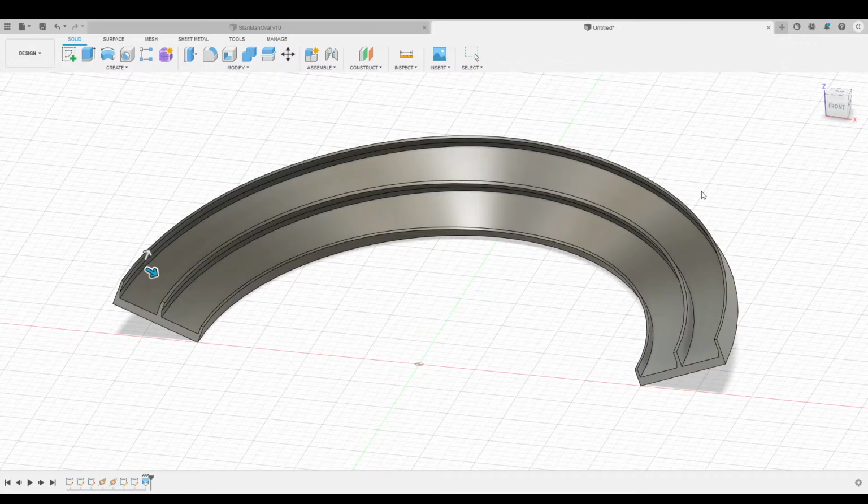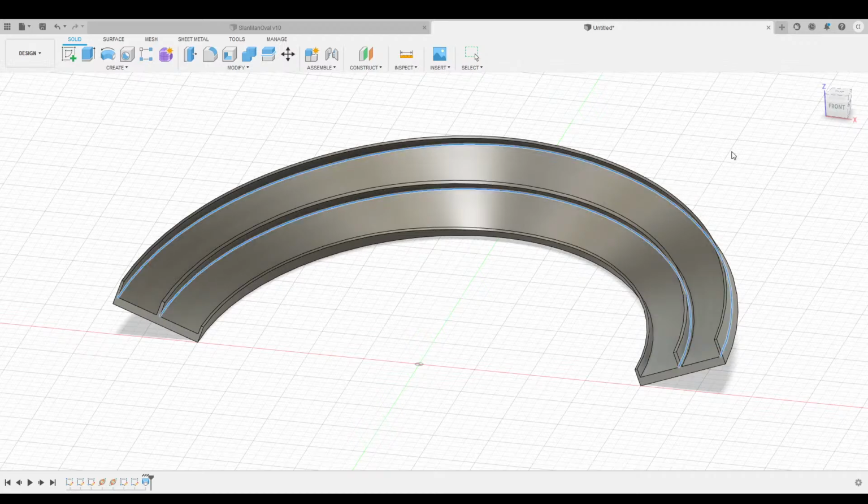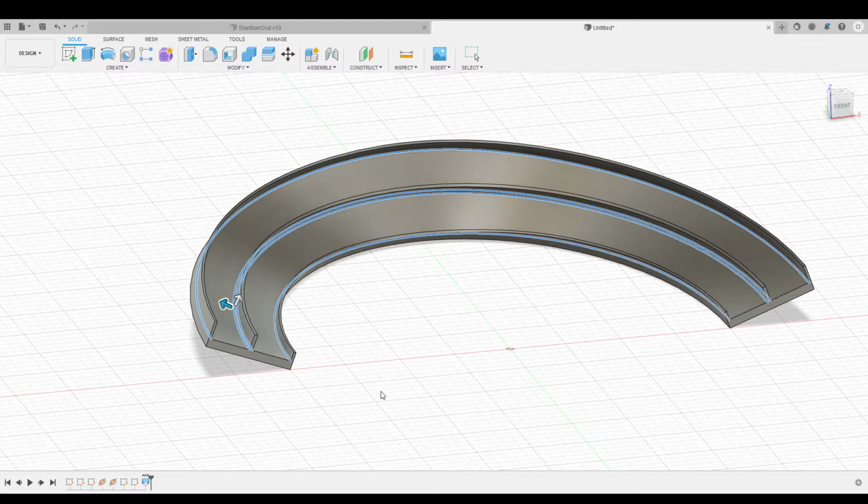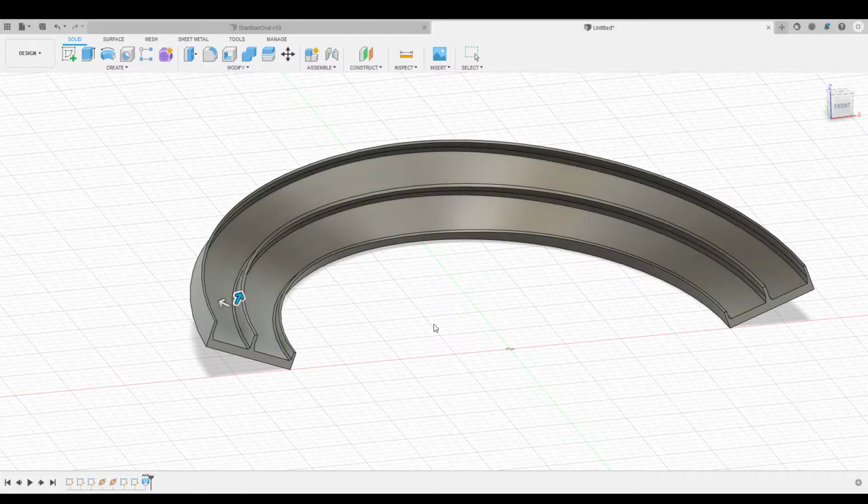And then we click plus to add a new set of things we're picking, and we'll pick the other lanes, or the other side of the lane, I guess. The arrow is highlighted as blue, so when we're doing width, we're going to do taper width, hit tab, taper height.